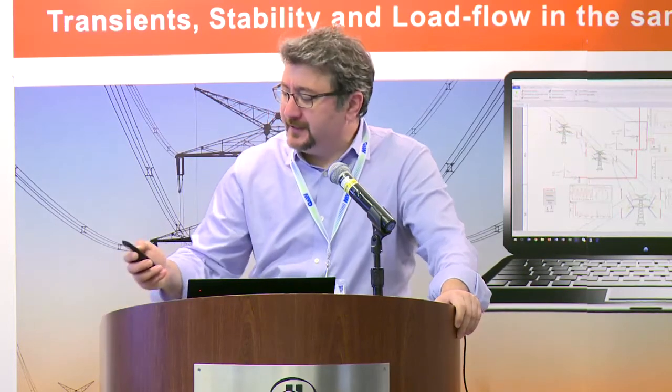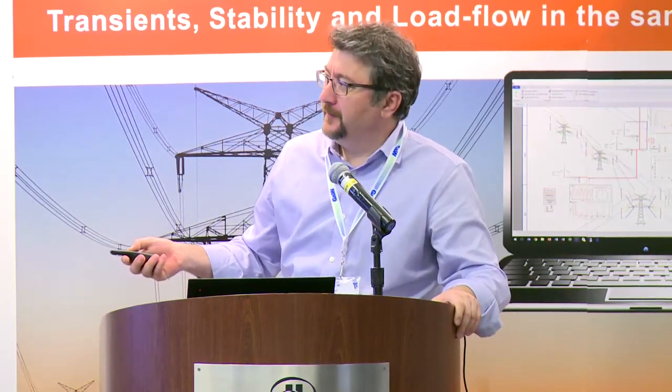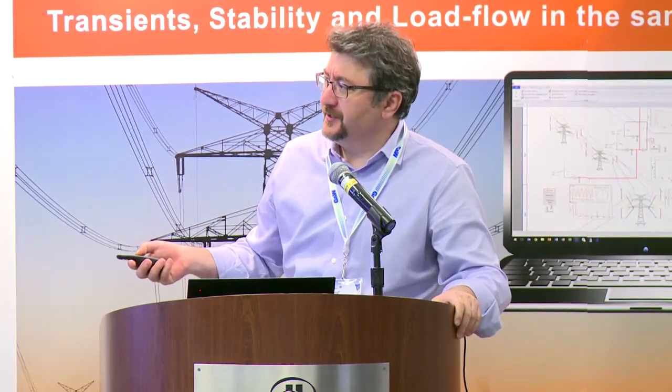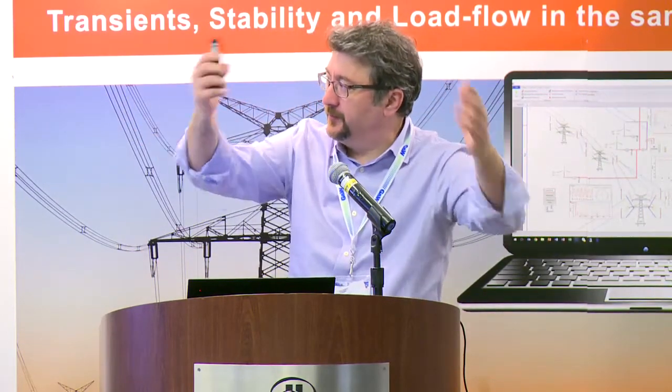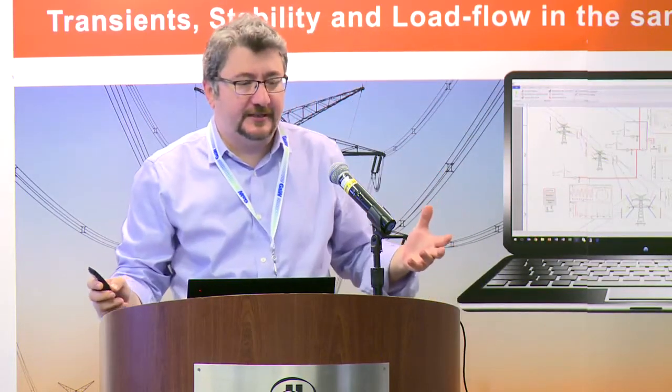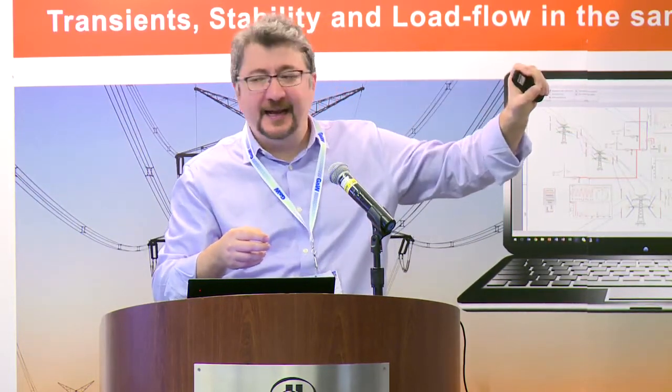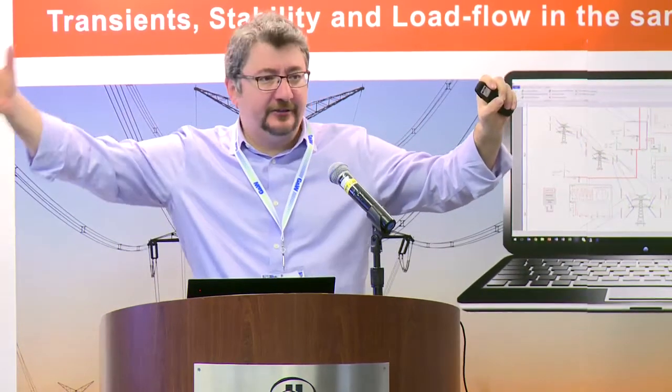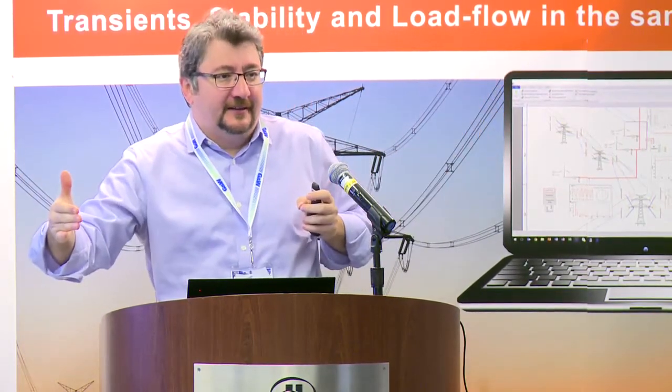And also, because you have a propagation function in time domain, of course, you find the solution with convolution. It is, again, in the theory books and everything. But the problem is you have interpolation errors. Why? Because you need the past values, right? The conditions at one end of the line depend on the conditions at the other end, but with a time delay, right?